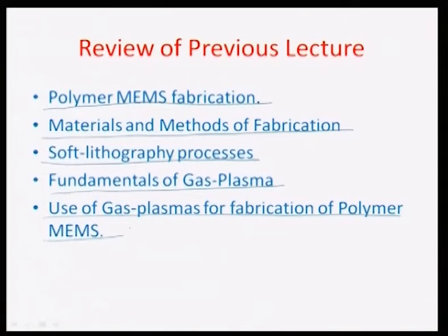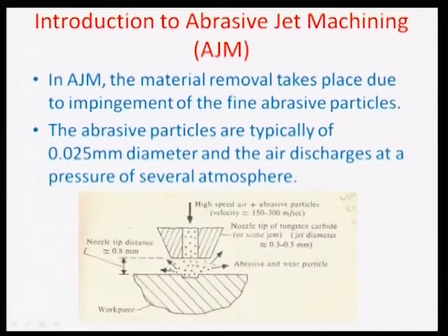So today we will look into one of the first fundamental mechanical non-conventional processes called AJM or abrasive jet machining. As I have already illustrated in my previous lectures, the non-conventional domain can be split into mechanical removal of material, thermal removal of material, or chemical and electrochemical removal of material, meaning that the way in which material removal takes place by supplying energy of different forms makes these categorizations happen.